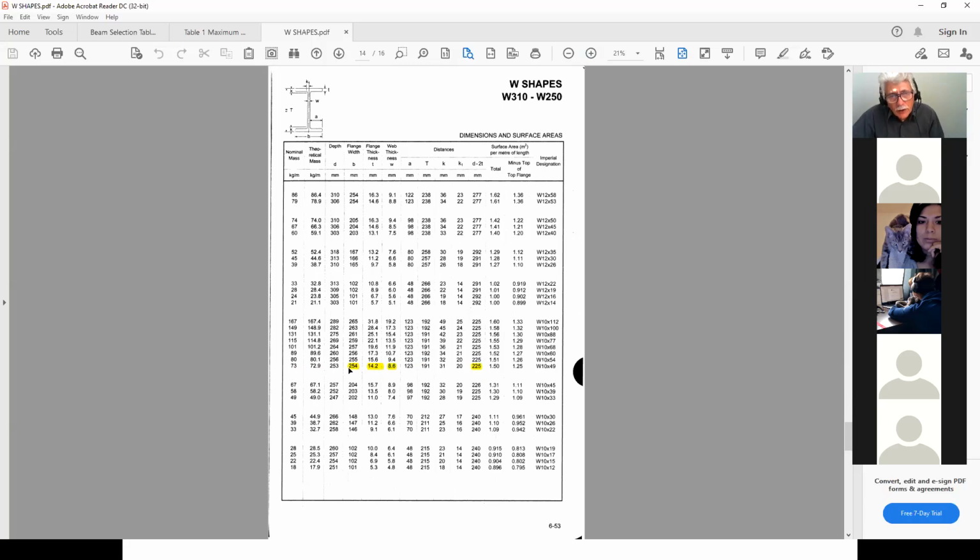So this is the check for the BEL over T value here. I take my B value divided by 2. T is the thickness of the flange, you see it here, and of course W is for the web. We also have to check the web, and this is the height of the web, so it's H over W. This has to be less than the value that we have in table number 1. And BEL, which is B over 2 divided by T, has to be less than the value in the table.